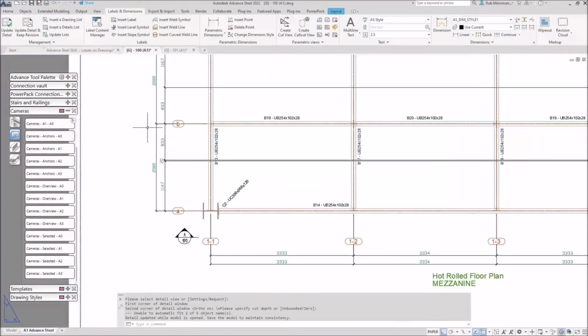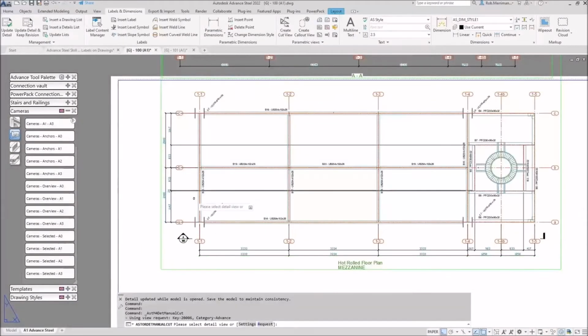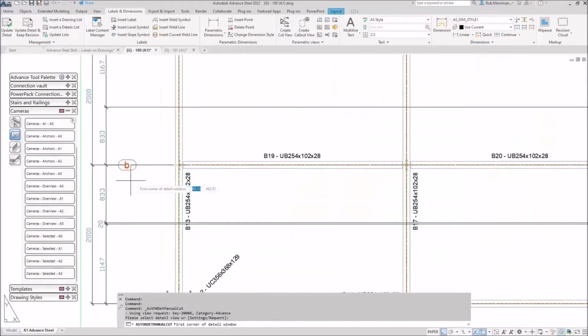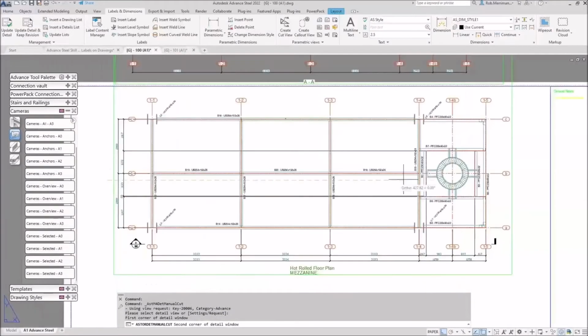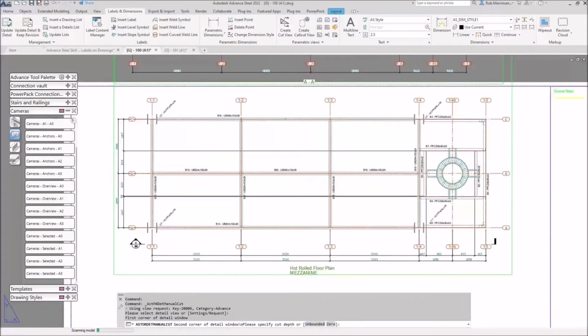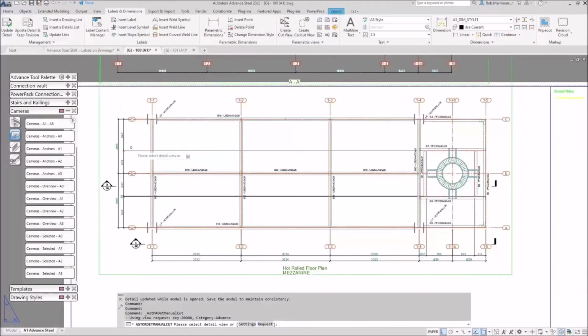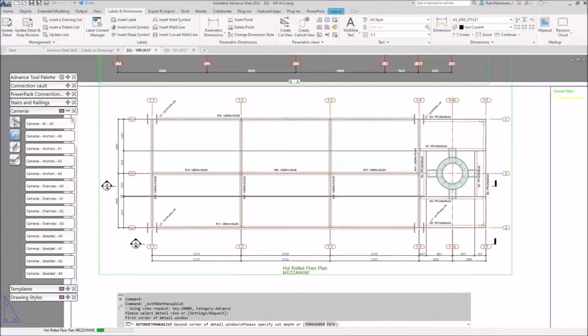And a year or two ago, can't quite remember off the top of my head, the system did add some new section arrows in. So if you're doing sections on GAs, you will get a different arrow than if you're doing sections on part and assembly drawings. There are management defaults to control that, and there's also symbols associated with everything. But what I'm doing in here is I'm adding my cut views in, and you can see that wherever I start my window and end my window, that is where the arrowheads align to.